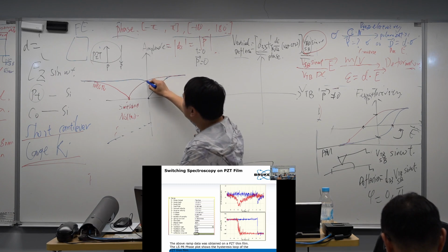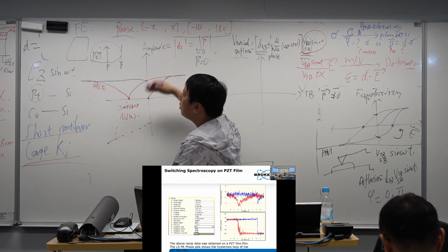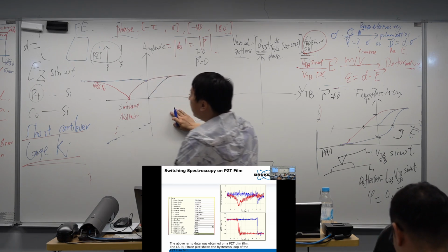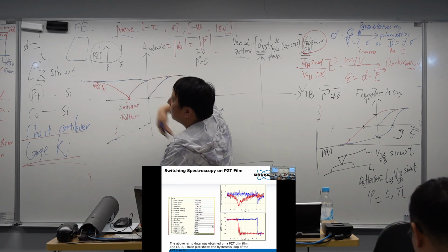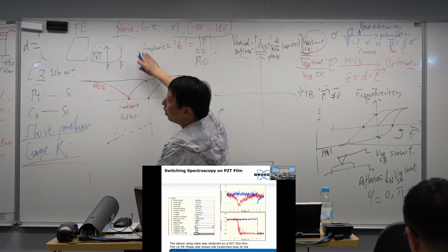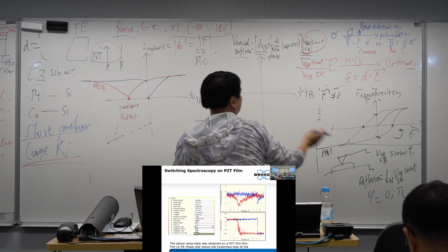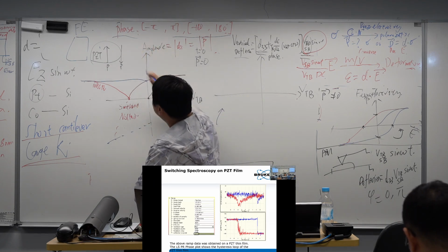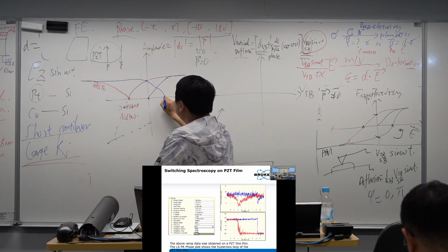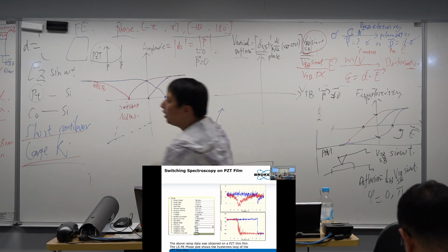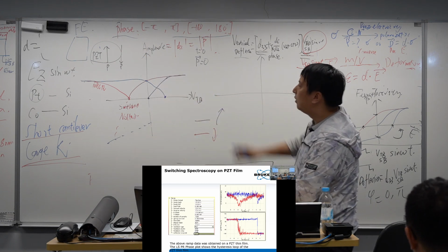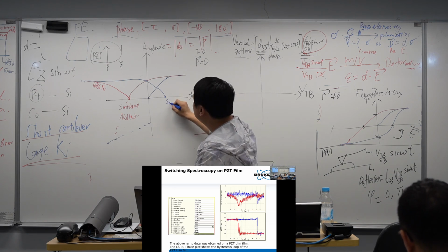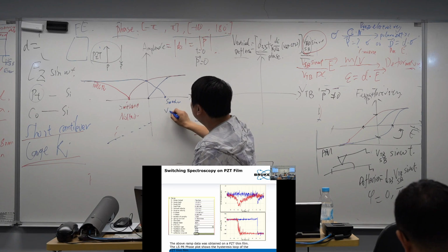And then I continuously increase the voltage, the facing down turns to facing up. So the total polarization is increased, but the absolute value of polarization is reduced until it reaches another coercivity. On this axis is voltage, so it's another switching voltage.